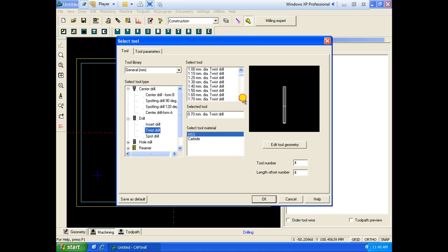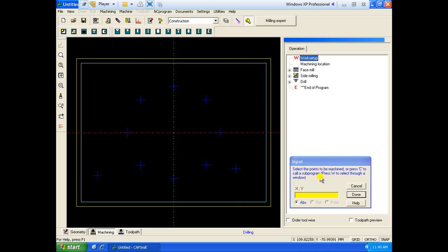With a 1.5 pitch, 8 minus 1.5 is 6.5, right? You need to select the 6.5 diameter hole in order to machine it. Select that, okay? Select the 2 holes where we require this on the object. Now select that particular hole exactly.